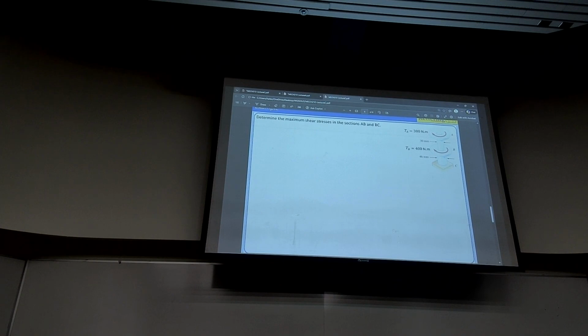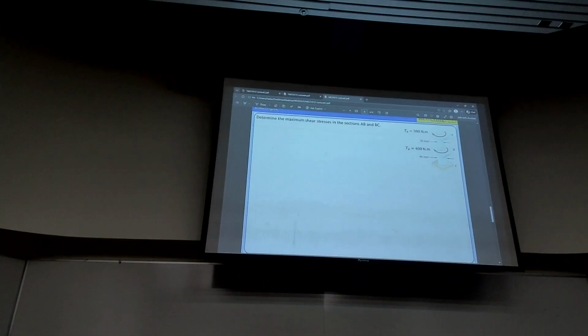So we said in practice we can figure out whether this is made of ductile material or brittle. Suppose I twist it and then it fails. You look at the fracture surface, and by looking at that, you can comment whether this is this or that. What is that? Ductile would be completely straight, basically, and then brittle would be 45 degrees. Very good. Is it only this or what about this? It could be both. Very good. It could be either. All the points.